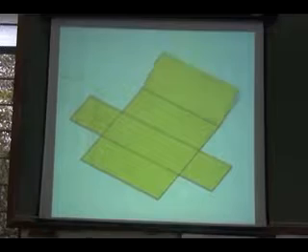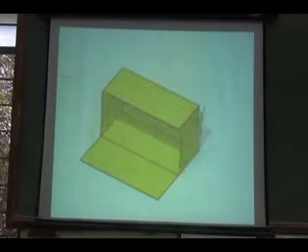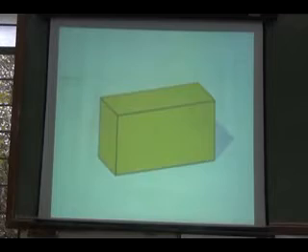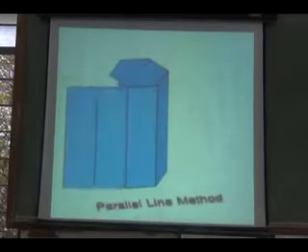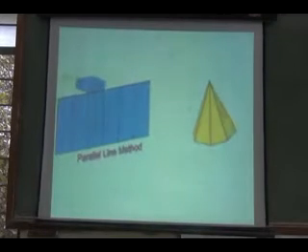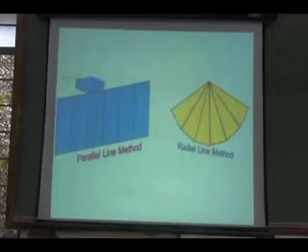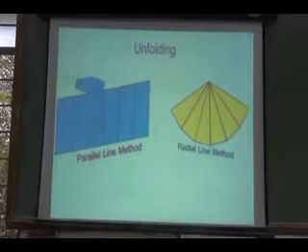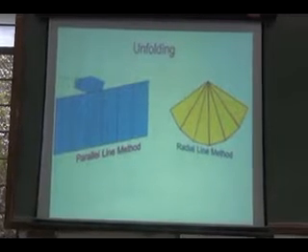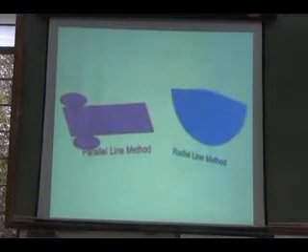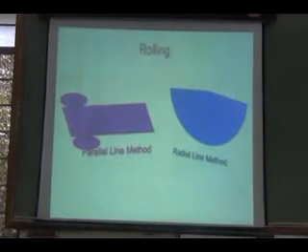If I fold it again and weld it, I will form the square prism. Similarly you can have a hexagonal one. For prisms and pyramids, I have to unfold; if it is a cylinder or cone, I have to go for a rolling process to get the required shape.